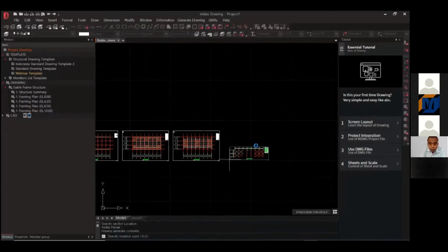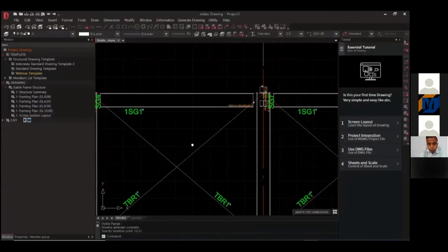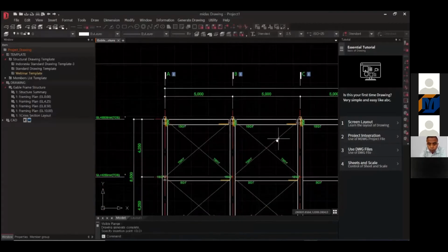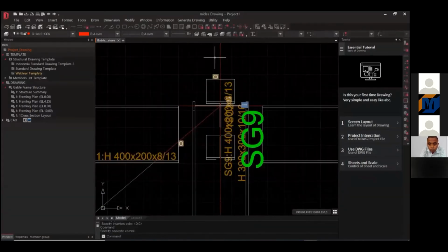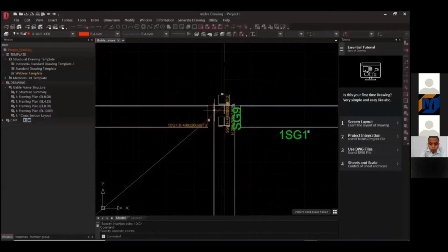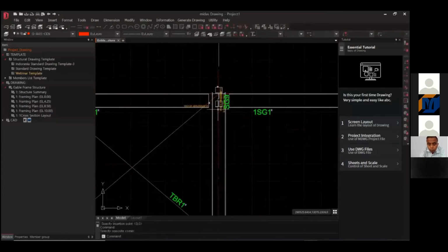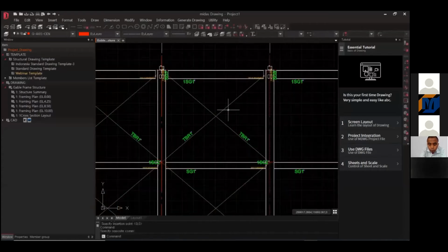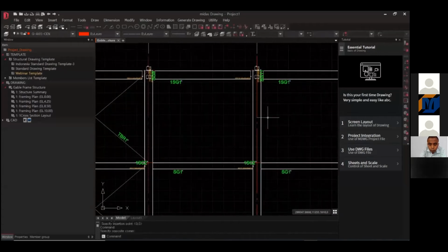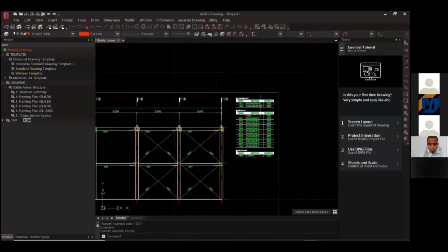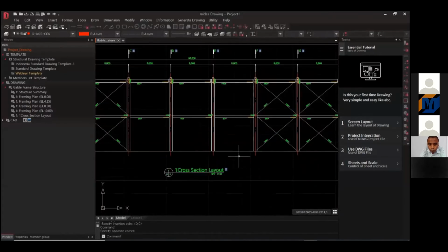Once the section is extracted, place it in the appropriate location. In the section drawing, the rest of the members except for the brace were printed as double lines. Also, check the layers. Horizontal beams are arranged according to TOS. Each member group name is also displayed. Section offset and start end offset of the members are displayed in accordance with the modeling information.